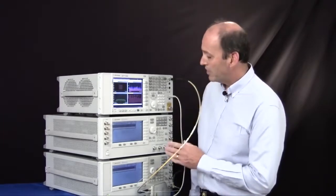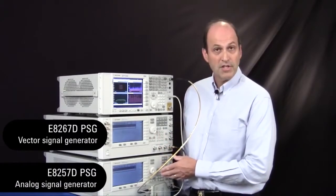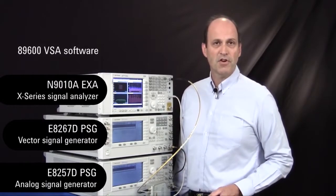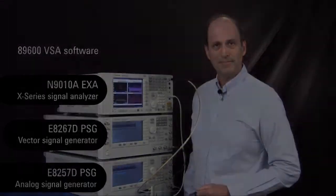To do that, we'll be using a PSG vector signal generator, a PSG analog signal generator, and an EXA Signal Analyzer running the 89600 vector signal analysis software. So let's take a closer look at how to set up this measurement.